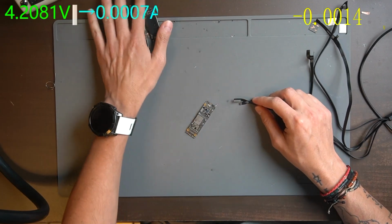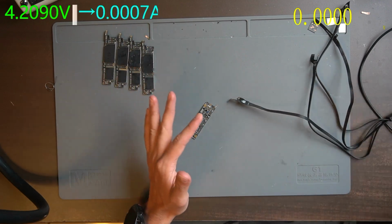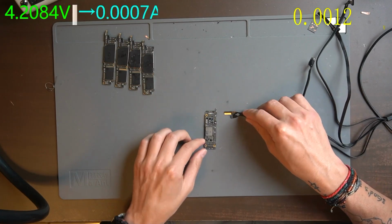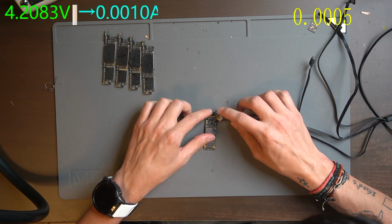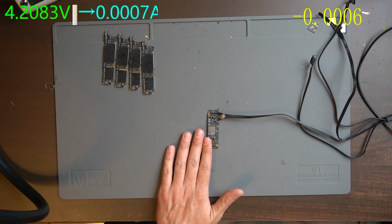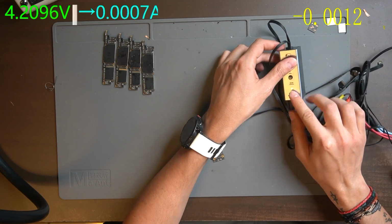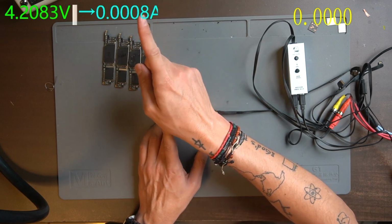So I have here some motherboards. I have 5 different motherboards to give you this example, okay? This is an iPhone 11 and I have some motherboards of iPhone XR. I'm going to do the example with the iPhone XR because I don't have too many boards right now, okay? But it's the same, it's the same for every board, okay? So I connect the power supply, and if you see right here, I have this one on, so I don't have any initial consumption, right? I don't have a problem with the principal lines.